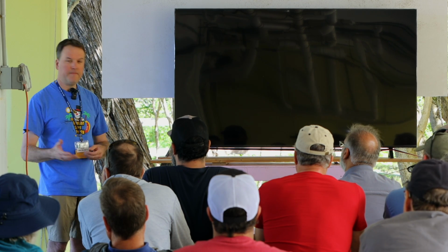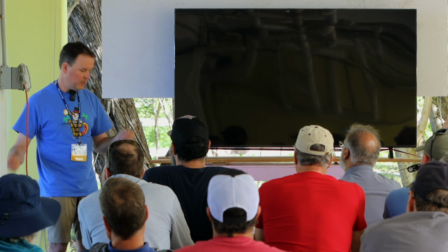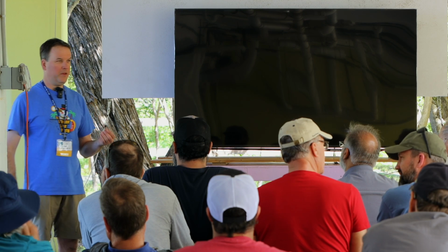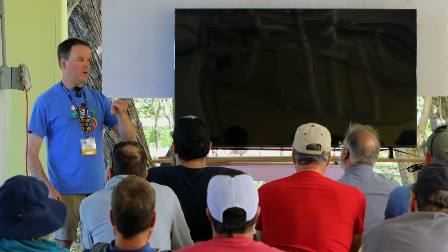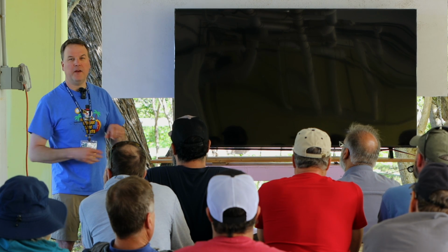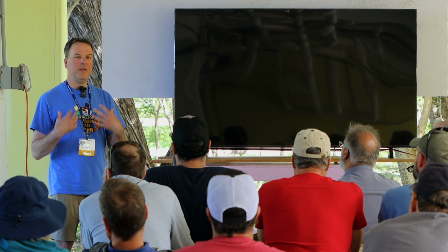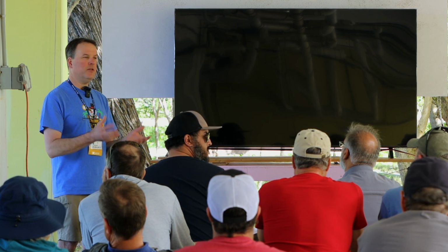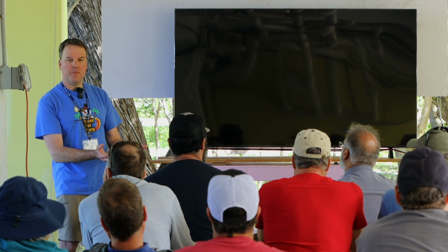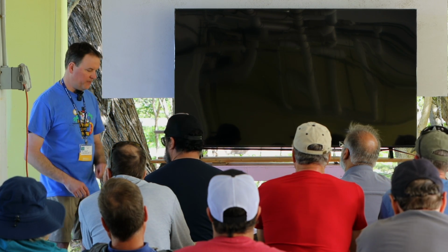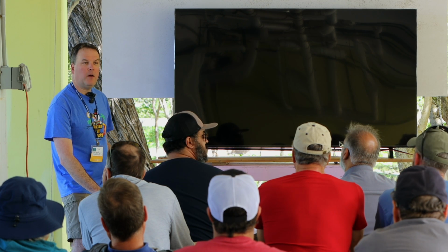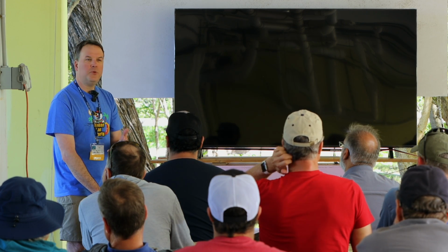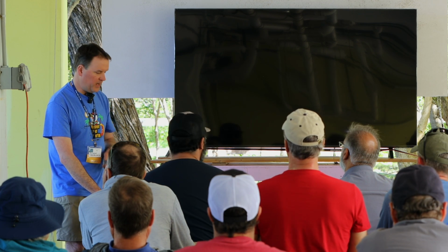Mirrors stick to their supports, and the reason it becomes a problem is because of the expansion and contraction. It doesn't take a lot of force to bend glass. That's one of the key things to realize, especially when you're, I will show a video if we get power back here, if we figure out a way to do this, of glass actually bending due to thermal changes, due to the heat distribution within a mirror being transferred to another mirror, and eventually they come to equilibrium. That's a flat mirror. So if you're gluing a mirror to something, you want to match that material, carbon fiber, maybe Invar, as close as you can to the actual piece of glass that's being adhered.